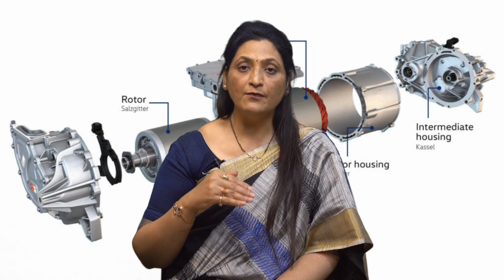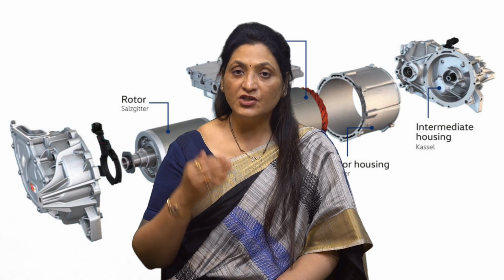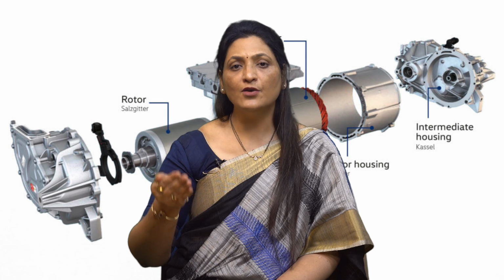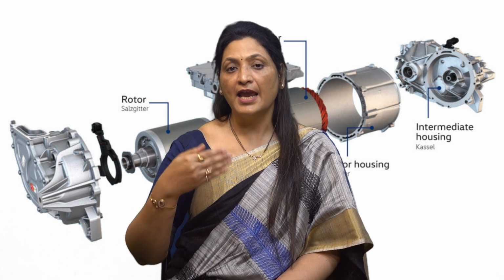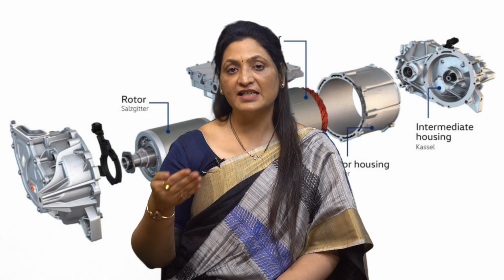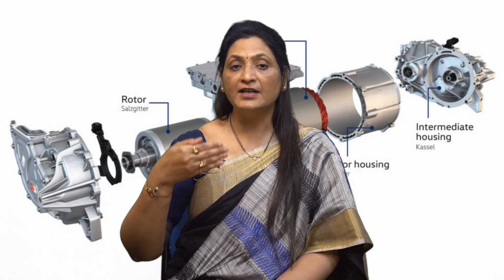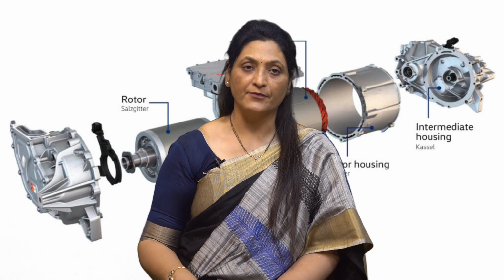Hence, the type of load and the running power factor of the motor are the essential considerations while selecting a drive. There are a variety of types of load conditions possible, like continuous, intermittent, impact, etc., and such load variation factor and duty cycle of the motor influence the selection of the drive.